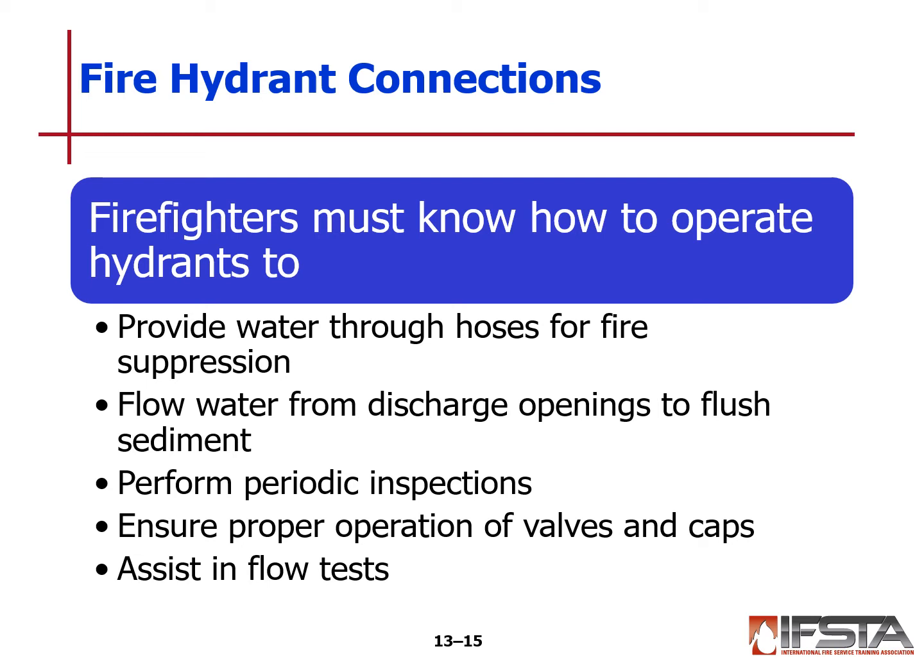With our hydrants, we want to perform periodic inspections. A lot of times in a lot of bigger cities, the water companies take care of this. They keep really good records of the flows, the static and the dynamic pressures, and they let us know what those are. We also want to ensure proper operation of the valves and the caps. So when those get checked, if anything needs to be lubricated, it's done at that time. We want to make sure that we can get the caps off in a hurry, and that the valves and the valve stems operate properly.